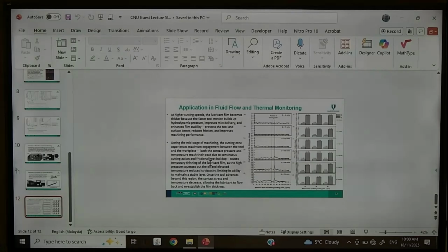Because for this technique you can measure multiple planes. You can use various lasers and combine them with various dyes, so you measure what you want to measure, and you can combine it with another visualization method to measure the other properties. And this is not intrusive. Other methods may also be non-intrusive, but this one will not change the liquid properties itself. You can just get the optical change of the liquid fluorescence from the dye activation.